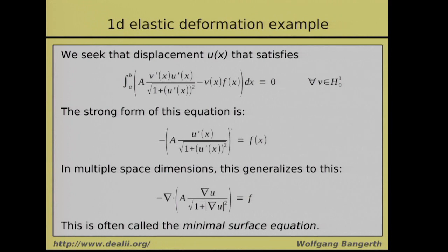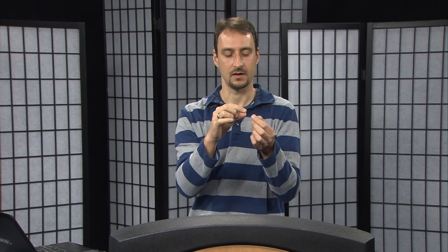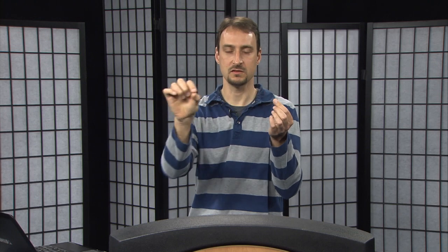So let's say you have your membrane, and instead of a drum where the vertical displacement is fixed at 0 all along the perimeter, you deflected the clamping at the edges, so let's say you have something like a soap bubble or a soap film that is spanned by not just a circle, but by something that also has a vertical displacement. So the boundary values are not 0, but they are in fact something that moves up and down. Then this is the sort of equation that describes the vertical displacement of the soap film.